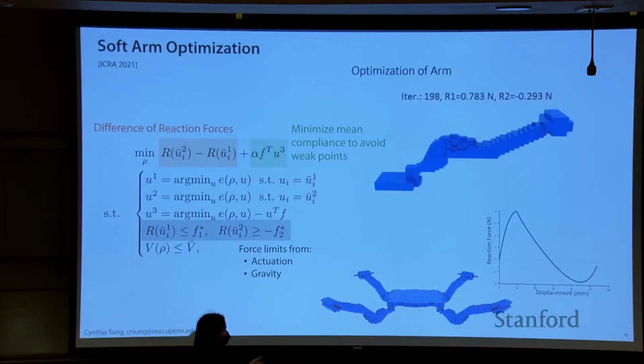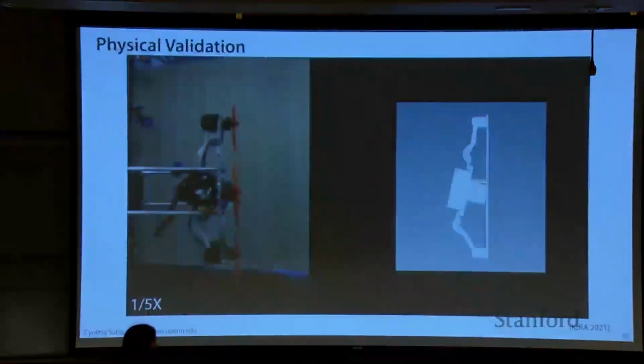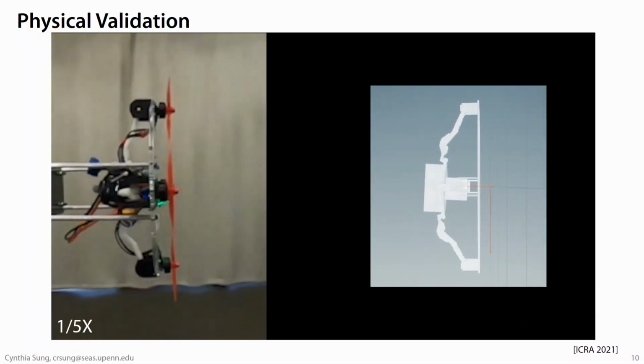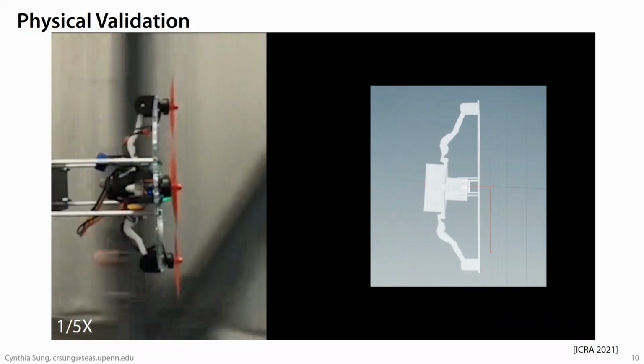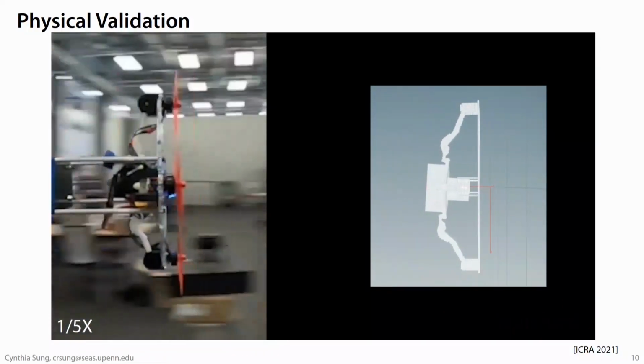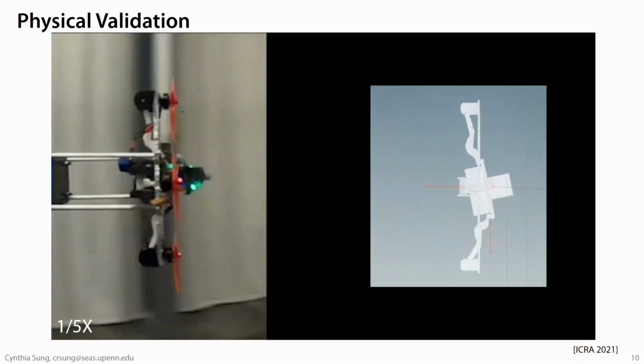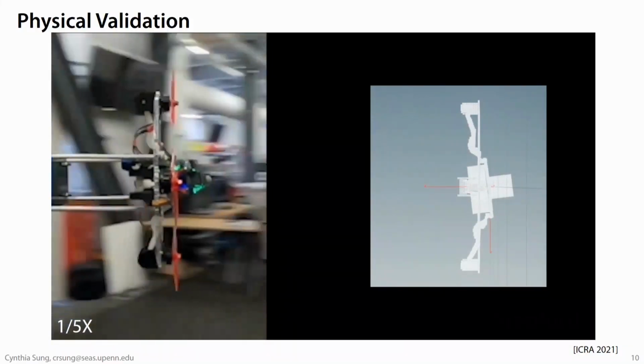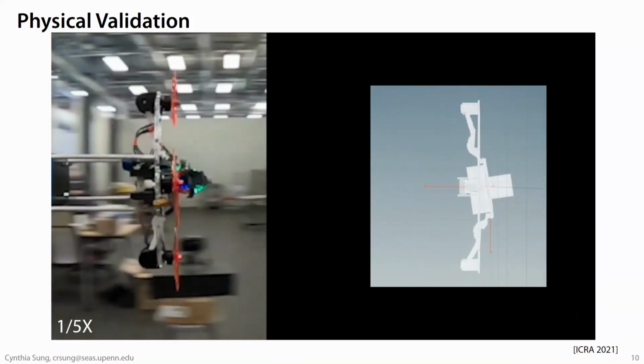And we said, this is really great. We didn't actually have to do any of the manual design ourselves. Can we get this robot to actually work in real life now? And so we printed out these beams and attached them to a quadrotor, and had it accelerate. What you're seeing now is a comparison of the physical vehicle with the simulated one on the left. So this vehicle over here is going to accelerate, and now it's decelerating. The mass in the middle continues its motion because the actuators aren't directly attached to it. And as a result, the vehicle switches modes, right?